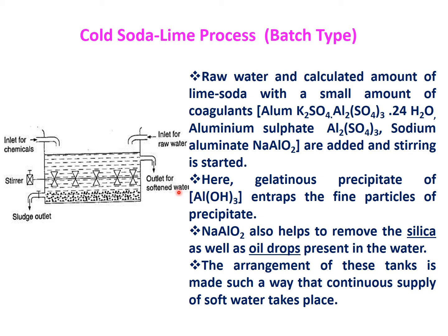This soft water outlet is designed in such a way that we can continuously get soft water. It is at some height from the bottom so that whatever precipitate forms by mixing the chemicals and the raw water will move towards the bottom